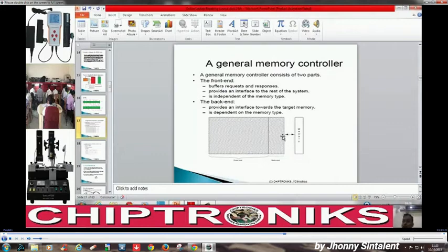So how does our GMCH IC know whether DDR3 RAM or DDR2 RAM is there, with the same GMCH? Because the GMCH is divided into two parts, front end and back end. Front end is the same: CKE, CAS, RAS, write enable for generating all these kinds of signals, and the back end is for the specific kind of memory.